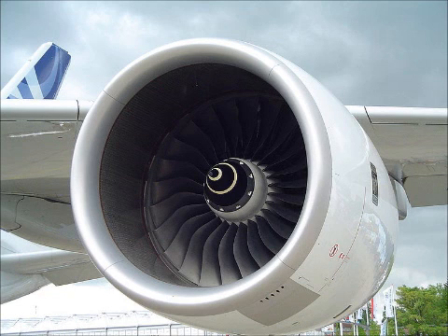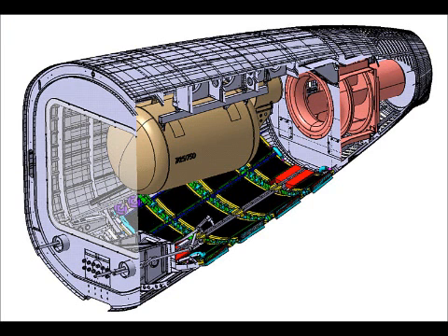Current turbine APU and turbofan engine have a Jet A fuel to electrical energy efficiency of around 15% and 40 to 45%. Proposed SOFC APU has a Jet A fuel to electrical energy efficiency of around 60 to 75%. However, current SOFC APU technology is not without its hurdles. At the moment, the main concerns with SOFC APU technology are its cost, weight and size.